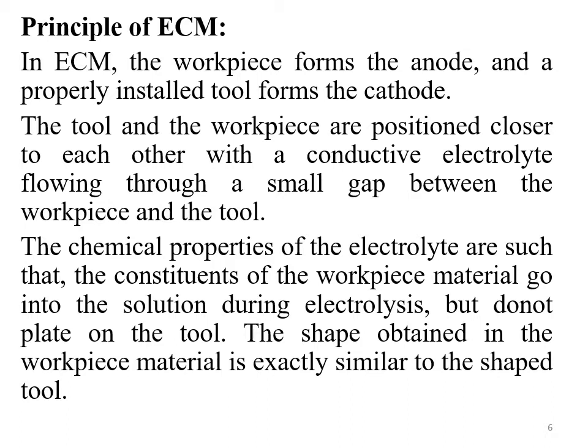This gap is very necessary because when we connect the whole circuit with two electrodes and dip both in an electrolyte, the circuit gets completed. These are the two electrodes: the workpiece is the anode and the tool is the cathode. When we dip both in an electrolyte, the whole circuit will get completed, and both need to be kept apart. If they come into physical contact, obviously sparking or arcing will be generated, and it will cause damage to the tool and the workpiece as well as to the whole setup.